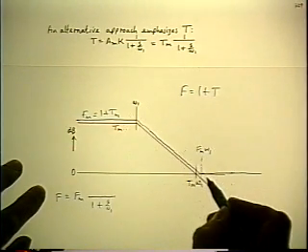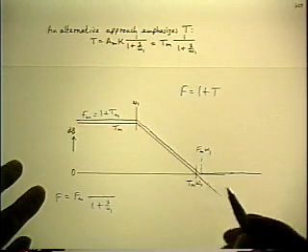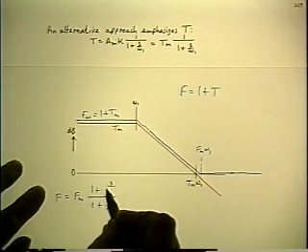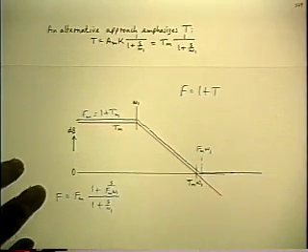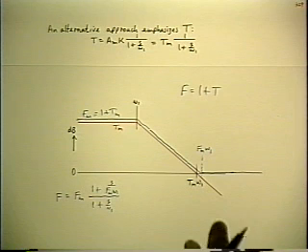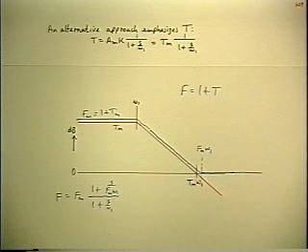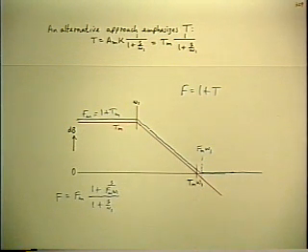You continue to look up, you see a concave upwards corner, so that's a normal 0 at FM times omega 1. That's the answer, quantitative, for the factored pole zero form for F, which has been derived by a geometric construction with no algebra.